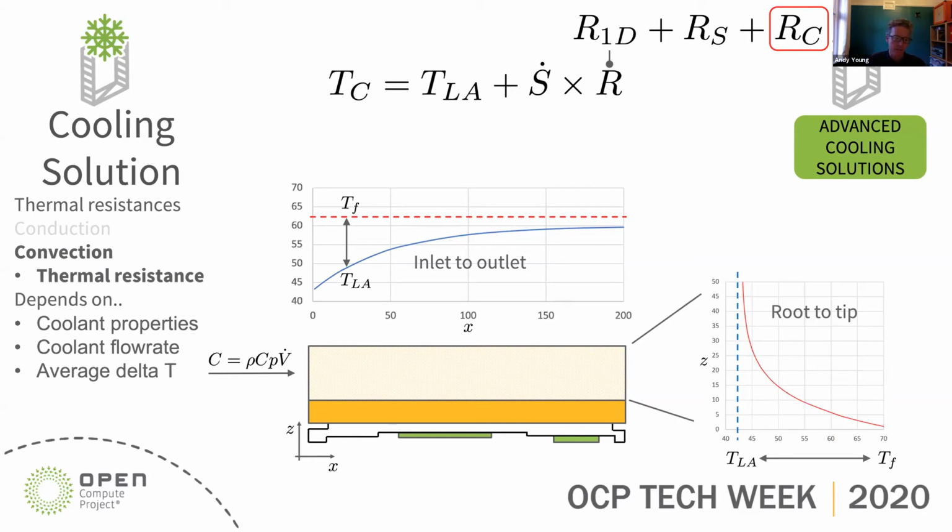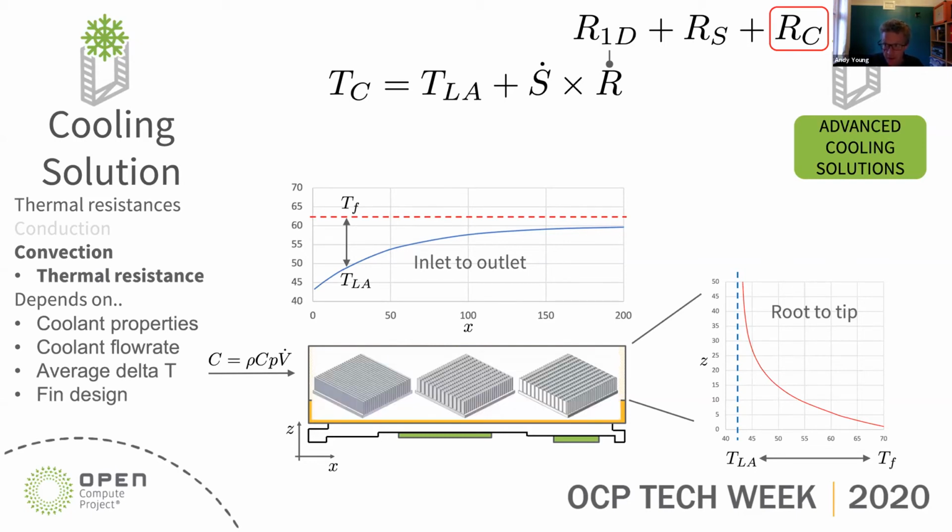Change the flow rate, change the heat spreading resistance, recruit more fins into the heat transfer package, change the fin design, you're going to see a big change in the performance. Imagine for immersion cooling, where you've got natural buoyancy causing the flow to move through the heatsink.